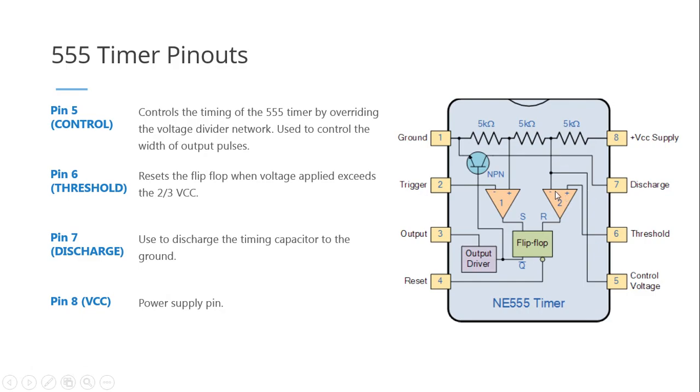And in the negative circuit here, we also have a connection, but this time around, it's 2/3 of the original resistance. So if there's 5 volts here, the one that would be going in as an input would be around 3.67 volts, which is normally the case. Then, depending on the trigger input and the threshold, it would control the duration, the duty cycle of the output in pin 3.